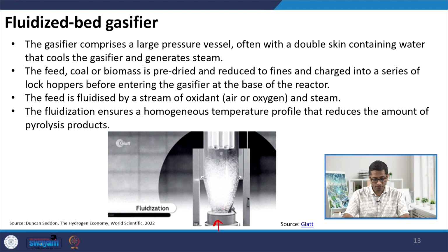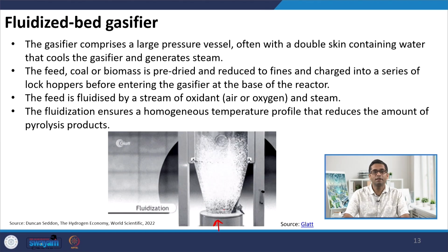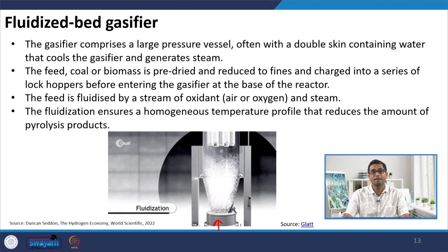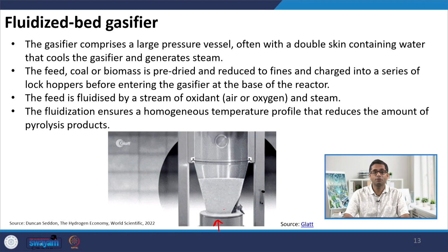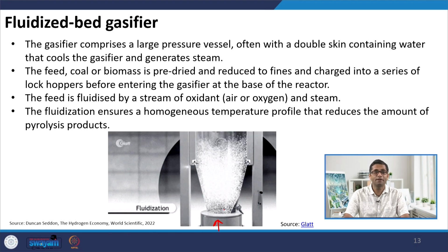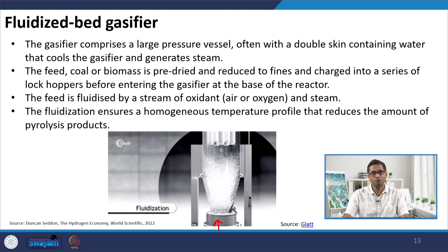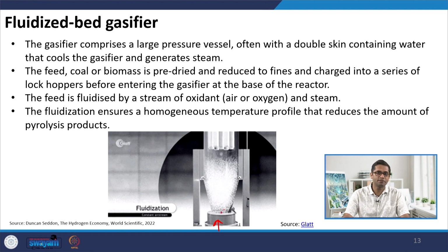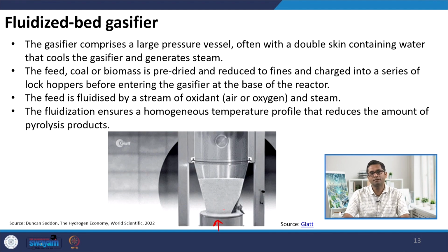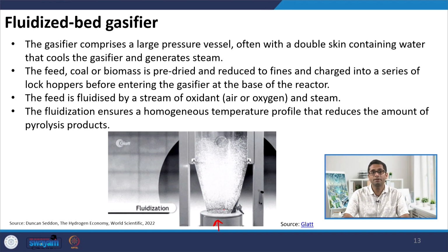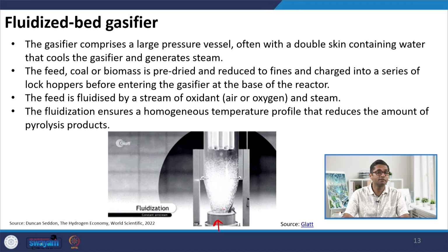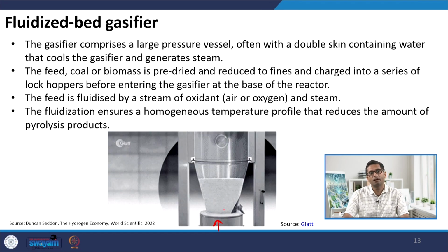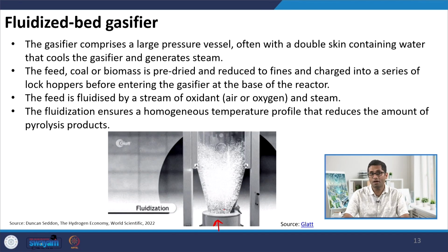Further, operation wise, it also has a bit of challenges in the sense that now the oxidizing medium has to play two roles. It has to provide enough oxidant to meet the equivalence ratio, and plus it also needs to be coming at a velocity such that the bed is in a fluidization regime. So control of this kind of gasifier is somewhat of a challenge, but if you talk about the larger scales, this kind of gasifier has been found to be economical and also has better performance, such that the syngas or the synthesis gas that I am getting is of a better quality with much less tar coming in.